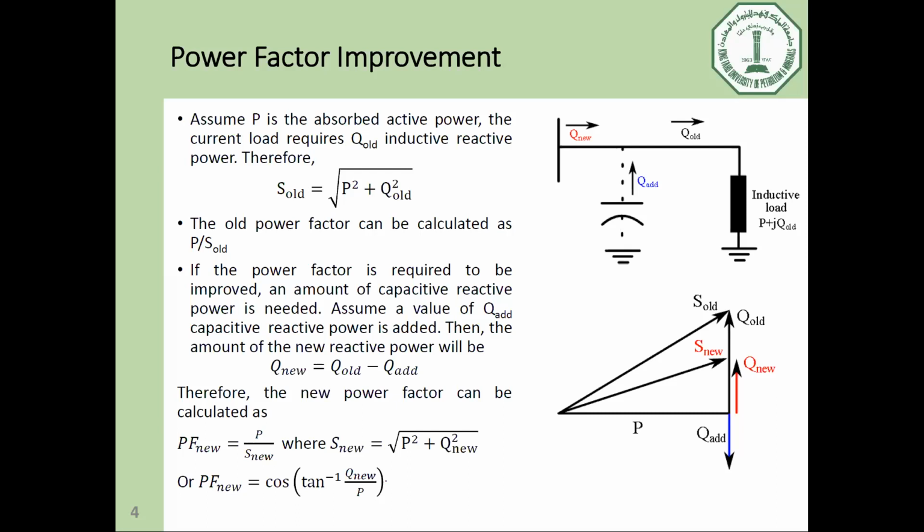a mode called synchronous condenser. It can also deliver reactive power. These are the old solutions. However, we have the most recent new solutions using power electronic converters. Okay, guys? It's called a static VAR compensator, or advanced static VAR compensator, which can deliver a source of power just by controlling the zero crossing of current relative to the voltage zero crossing.